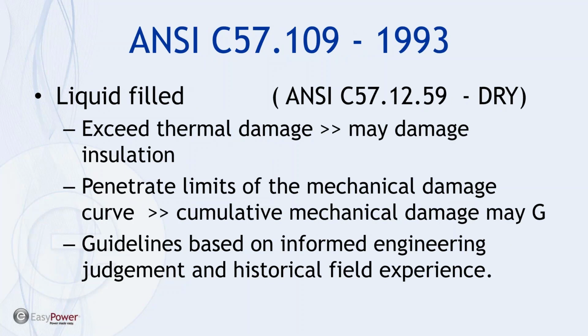In ANSI C57.109, and likewise in ANSI C57.12.59, there's a description of damage curves and how to plot them on TCC graphs that express the need to avoid thermal damage at the longer time runs and mechanical damage at the higher impulse current values.